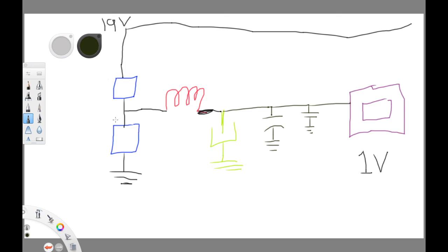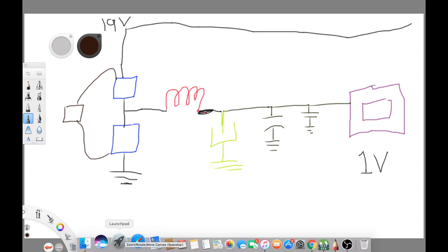And again, I repeat, these two MOSFETs are being controlled by the chip. There would be a chip controlling the switches. I told you the gates are switches. They are more like enable or disable. They are signals telling the MOSFET to allow power to pass or not.